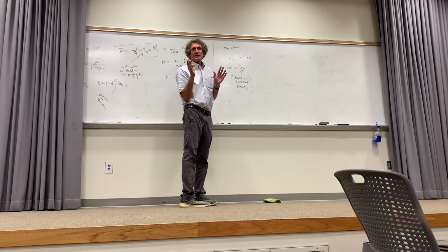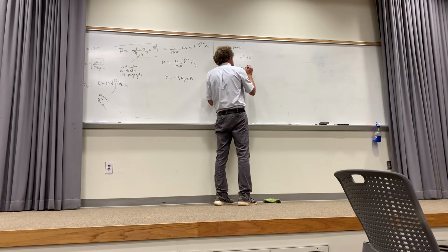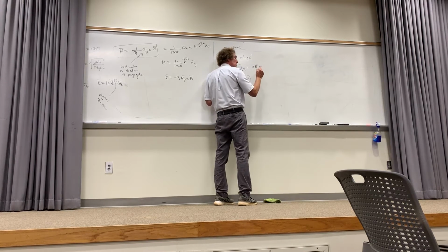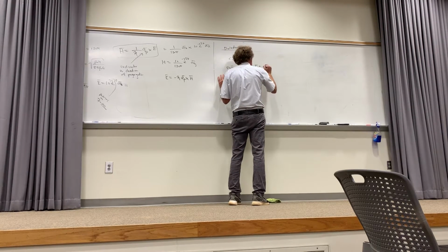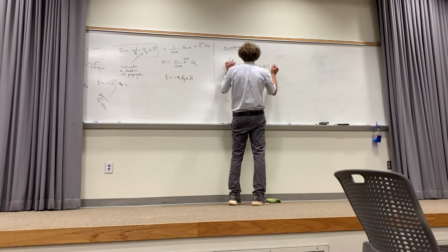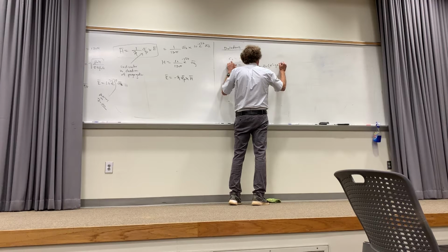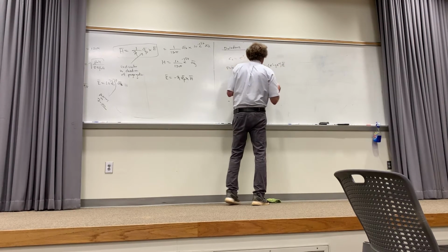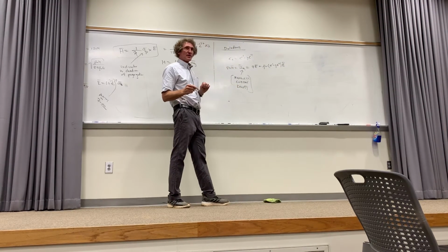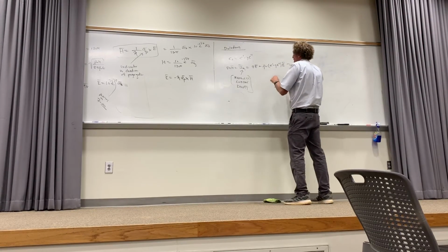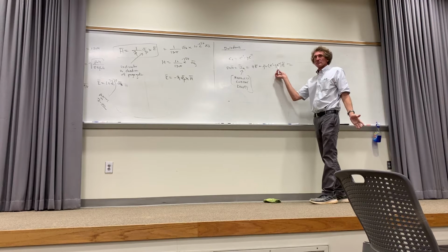Now, Maxwell current density is a summation of both the conduction current, so it's sigma E, plus the displacement current, which is plus j omega times epsilon complex, which is epsilon prime minus j epsilon double prime, times E. Just work with me here. You all see what I've done there? I've replaced epsilon with epsilon complex. What that does is this. What is j times j, anyone?